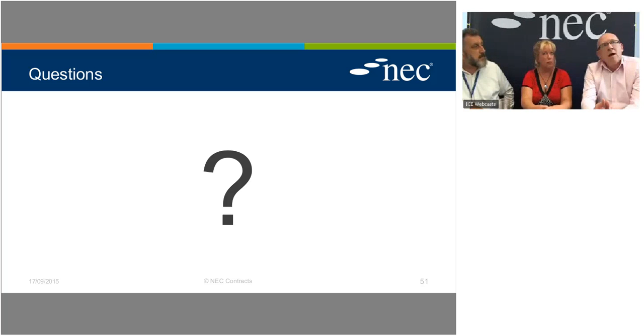Okay. I was thinking this next question, but didn't dare ask, so this is me and my DIY. How does CDM work in small domestic projects? That's a very interesting question, because CDM applies to all construction work, and knocking through a wall in a house, that's construction work. You are changing the fabric of the house.